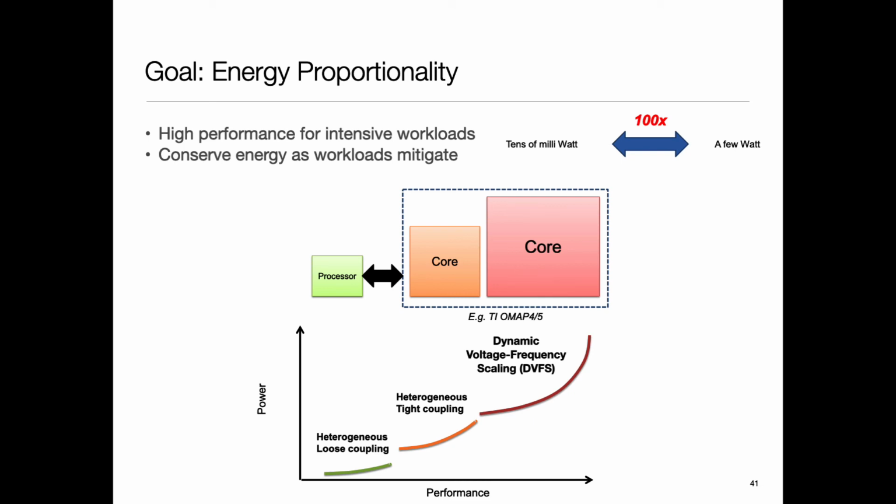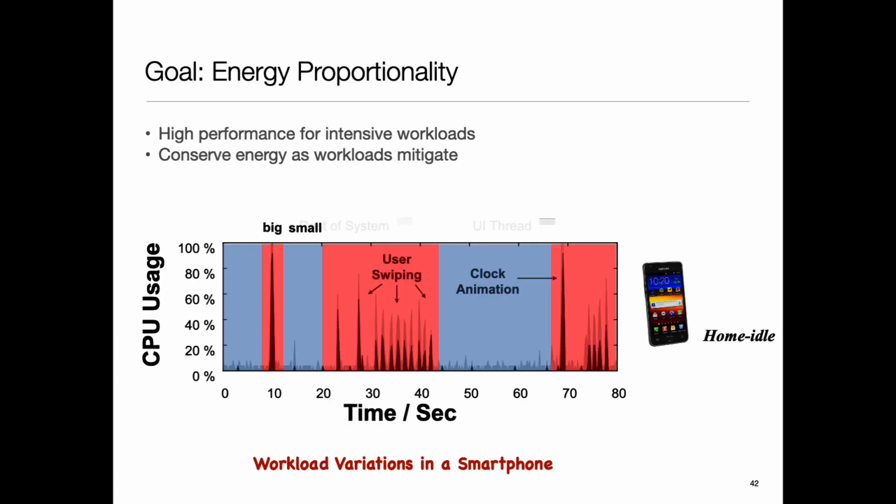Sometimes these heterogeneous cores may not even be programmable processors. They could be more like neural accelerators. They are programmable not in terms of writing a standard program, but configurable with, let's say, weights of a neural network. I gave an example of TI OMAP, which I think is already an example of it. I think some of the Amazon products use it, if I'm not wrong. But in any case, there are plenty of examples of these chips.